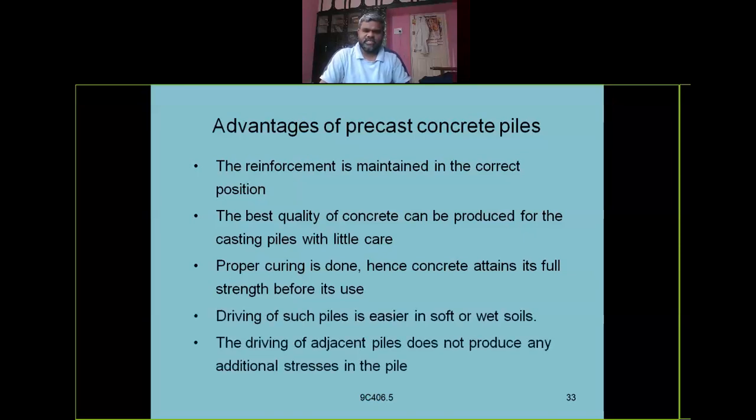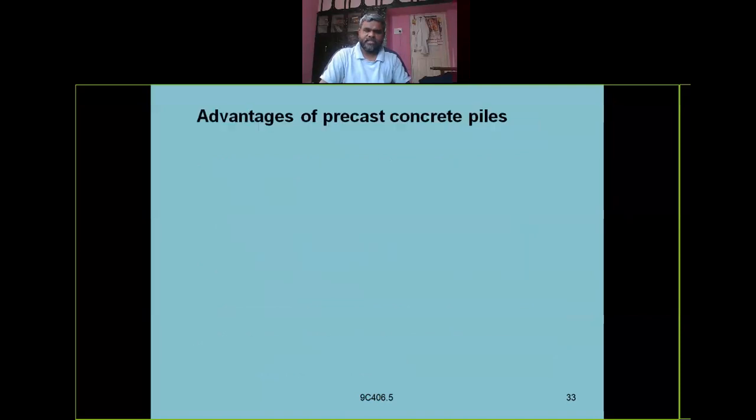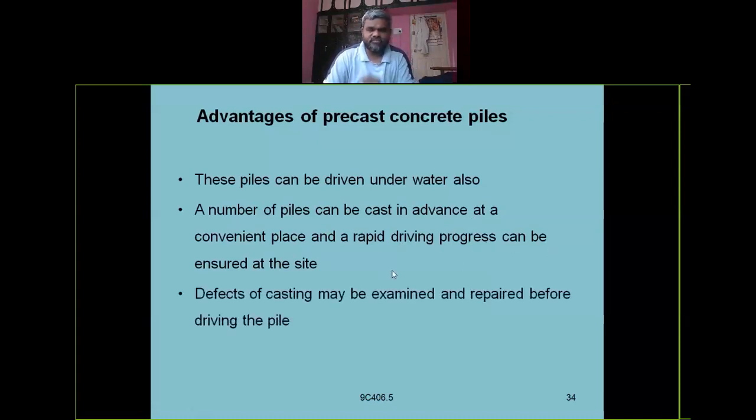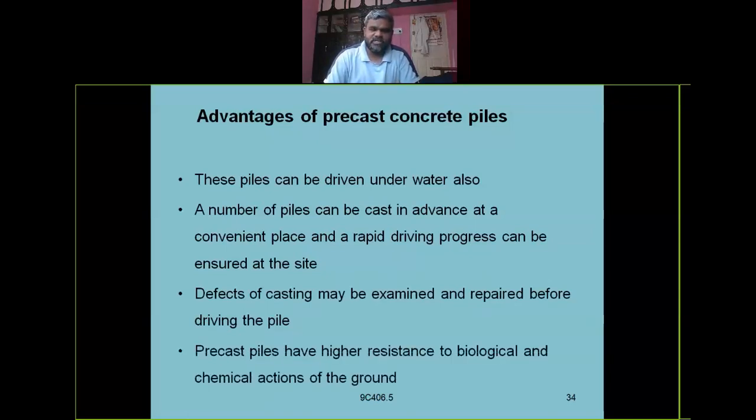The driving of such piles is easier in soft soils and wet soils. The driving of adjacent piles does not produce any additional stresses in the pile. The piles can be driven underwater also. A number of piles can be cast in advance at a convenient place, and rapid driving progress can be ensured at the site. Defects of casting may be examined and repaired before driving the pile. The precast piles have higher resistance to biological and chemical actions of the ground, because they were well cured before transporting them to the site, right?